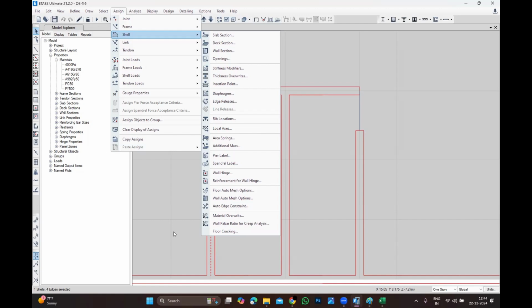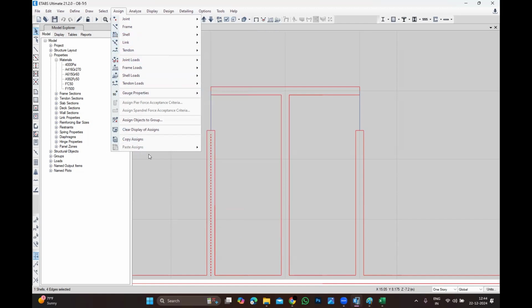If it were a wall, I would have only 12 millimeter or 16 millimeter vertical bars. The majority of the reinforcement will be vertical, and the horizontal shear reinforcement will be less, 8 or 10 millimeter. Here it was 4 bars of 25 millimeter, and they thought this was additional reinforcement. They demolished it, the hollow core slab sagged, and half of the floor itself went. And the DM has given them a huge fine.